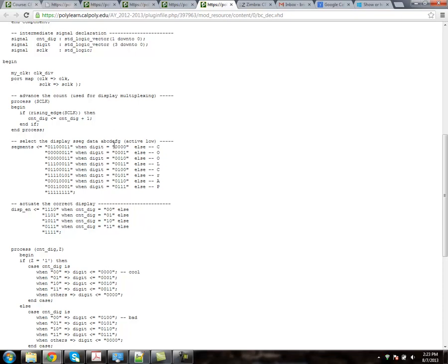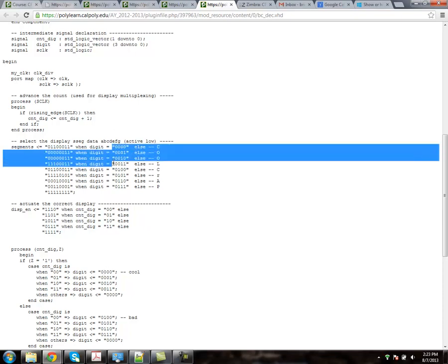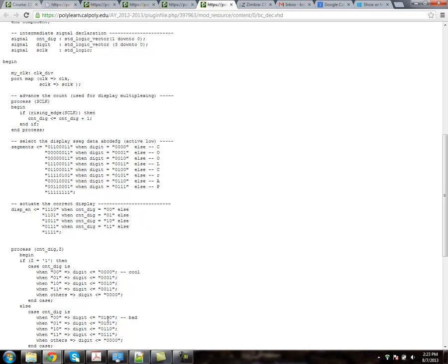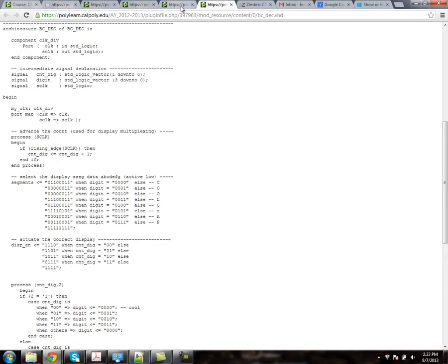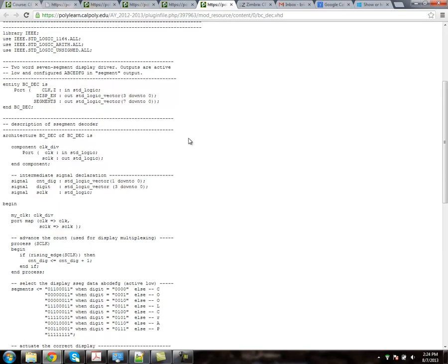As you can see, that matches these 0 through 3 up here. And if we don't detect the sequence, which is when Z is a 0, we're going to set the digits to display crap. That's 4 through 7, the same as 4 through 7 up here, to select the right segments. So that's what that file is doing, and I think this is a pretty fun lab and gives you other ideas of how to use the 7-segment display to show something other than numbers.